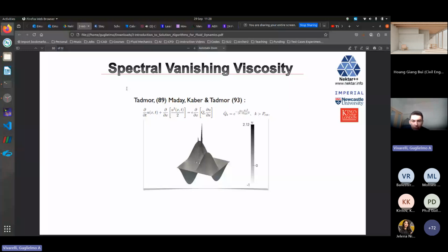So what you do is you have a filtering strategy, which is a Q kernel, which tries to determine which frequencies to damp. You don't want to damp the entire set of frequencies. You just want to damp the higher frequencies and have a cutoff, right? So you can resolve the lower frequencies, which are generally more easily resolved by a coarser mesh.